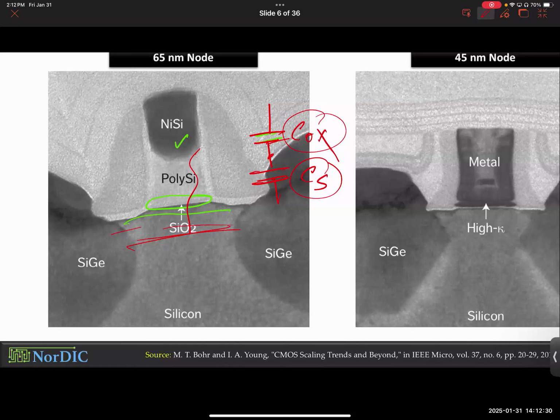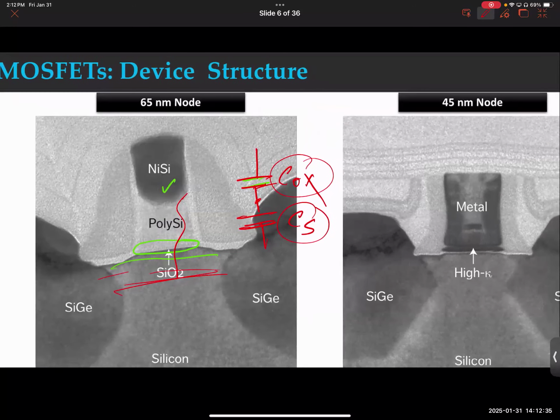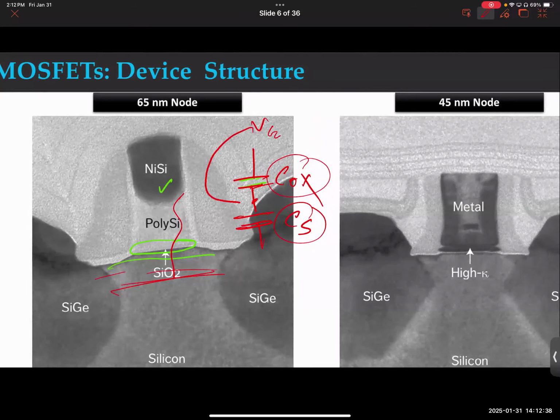Does that make sense? So basically, it comes from mathematics. What were we looking for? We were looking for, if you apply gate voltage, how much gate voltage will actually appear at the semiconductor, and how much of it will be dropped across the oxide. In making that calculation, people arrived at a situation where you had M equals 1 plus C_OX over C_S, something like that. Somebody wrote it as M at one point, but then it stuck. And they realized this parameter is the reason why you cannot have just any arbitrary subthreshold slope.